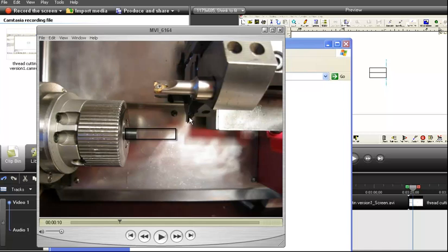And turning always starts from position which is defined as safe position, and this is true only for master tool, which represents exactly what I see in CAM, but problem is with other tools which have offset values to master tool. So we'll continue to show what is going on.